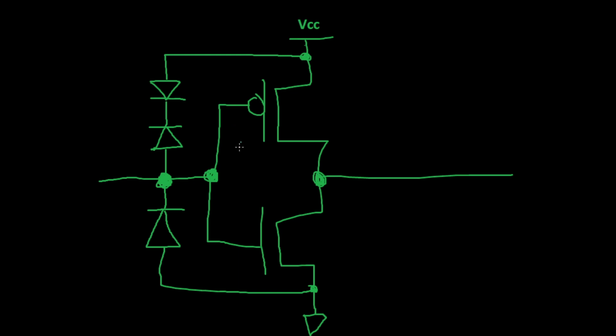However, most CMOS devices also have ESD structures, and these diodes typically will allow some leakage current. If there truly is nothing else connecting or affecting the voltage on the input, these diodes will quite often result in the voltage drifting to approximately VCC over 2 here, because the diodes will act a lot like resistors in parallel with capacitors. And this essentially produces a voltage divider circuit.